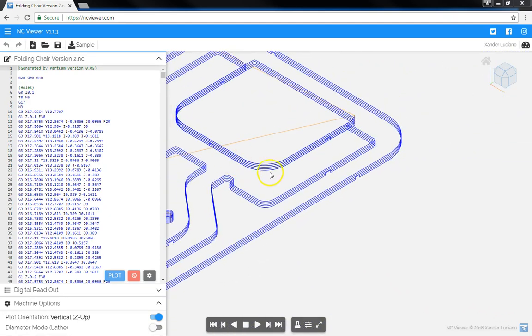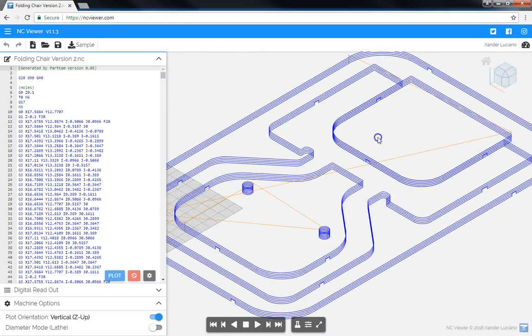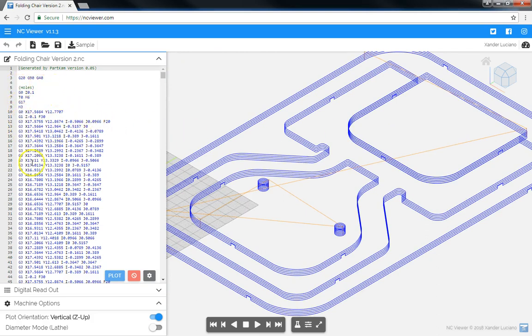Another thing to note, the only thing I've found so far that's really useful for being able to read Gcode is to find out the position on the z-axis. Like where it says G1 Z negative 0.1, that means it's going to be setting the router's position at this x and y coordinate, 17 inches over on x, 12 inches up on y, to negative 0.1. And then when I look down here further, the next z-axis instruction, it skips all of these pieces for z-axis instruction.